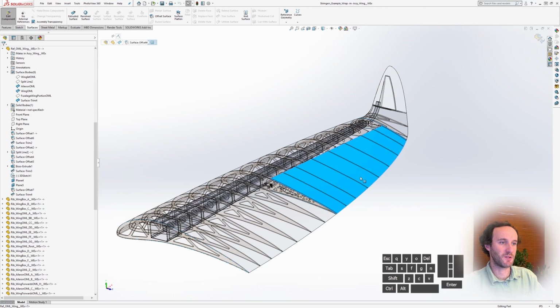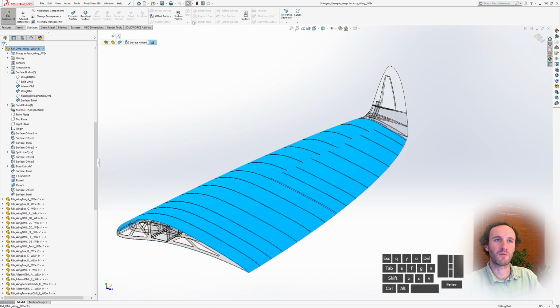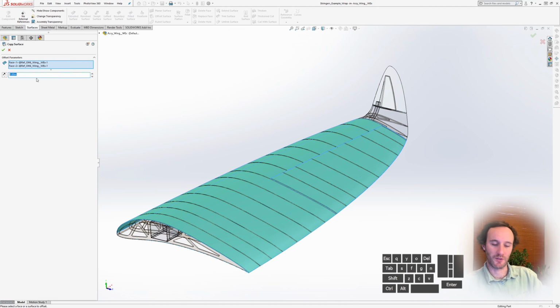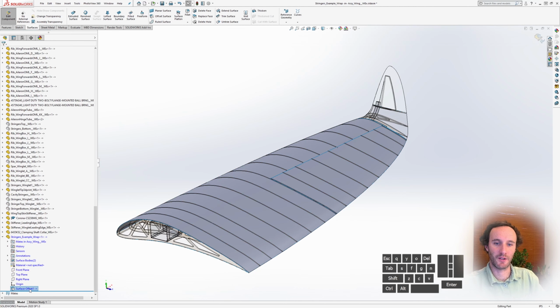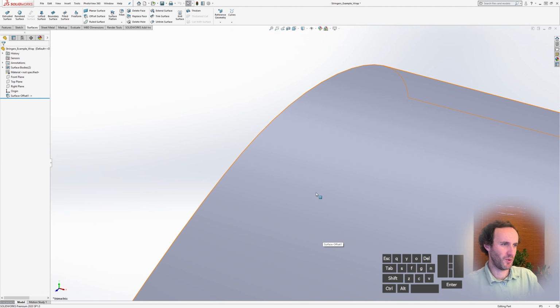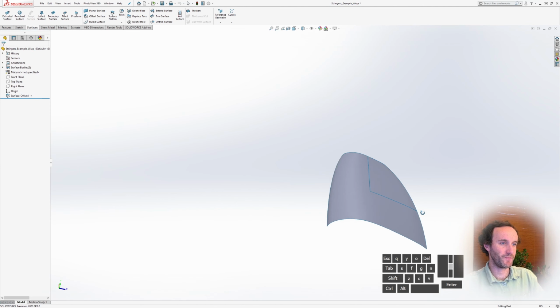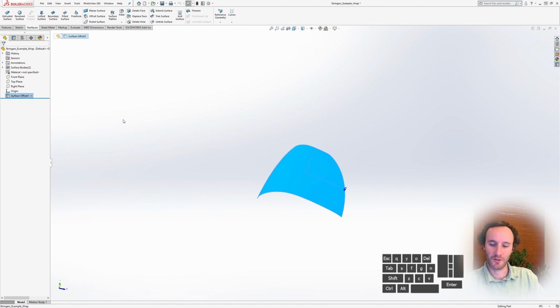So we'll take these two, go to surfaces and offset it. So 0 inches creates a linked copy, with, you can see this arrow on the surface denoting an external reference. So once we have those, we can open up our part. And so this will be our external ref surface.